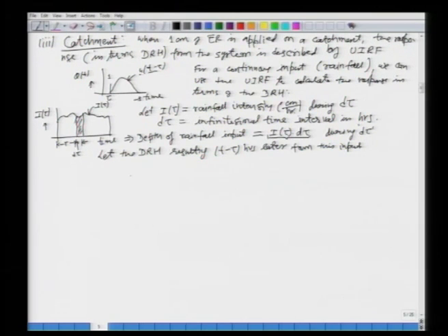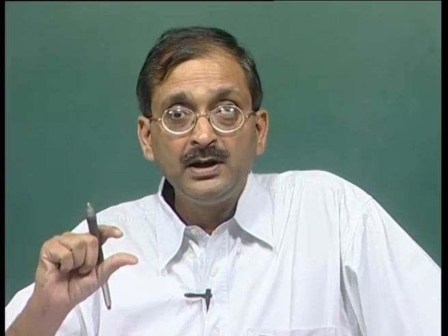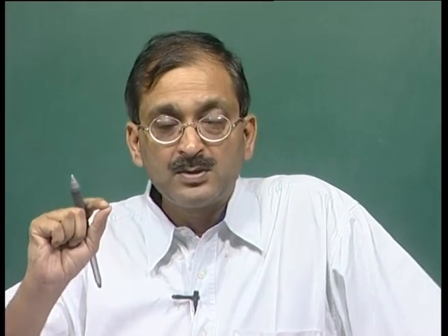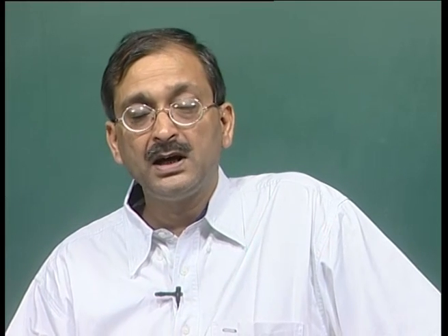Okay. Let us say that this is equal to small q of t. Okay. What will that be? I can use the principle of proportionality. I know the ordinate of the response from the catchment due to this 1 centimeter of rainfall. All right. So, given your u t minus tau, I can multiply each ordinate by the amount of rainfall, and the amount of rainfall is I tau d tau.